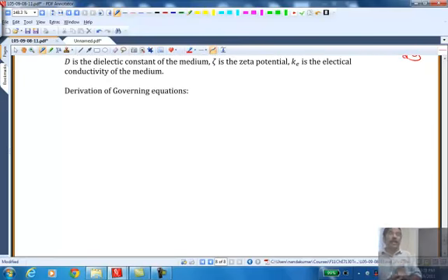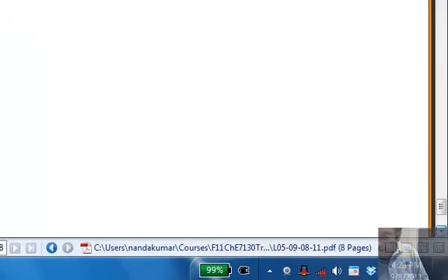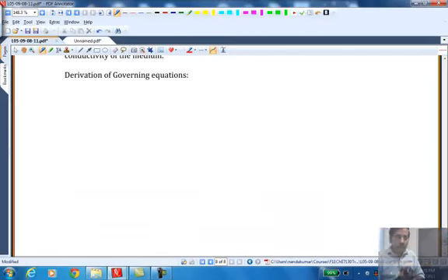So now starts the development of the equations of motion. We are going to start developing conservation laws, mass conservation, momentum conservation, that will give us the so-called equations of motion for the fluid, which we will solve later on. Now, in deriving these equations of motion, there are two viewpoints one can take.